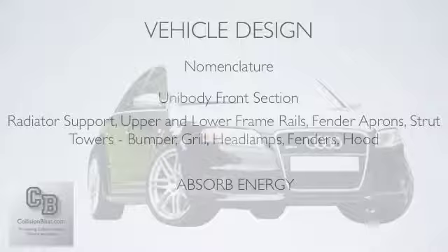So in the front, of course, you've got the bolt-on things. You have the front bumper cover, grille, headlamps, and you've got the radiator support. And the radiator support's actually part of your unibody. Now, whenever I talk about unibody, that's just the design. I've heard people say that unibodies don't have frames. Well, they do have frame rails, but what unibody means is uni means one. So it just means everything, including the frame rails, is welded together to make one piece, rather than body over frame, where the body bolts to the frame.